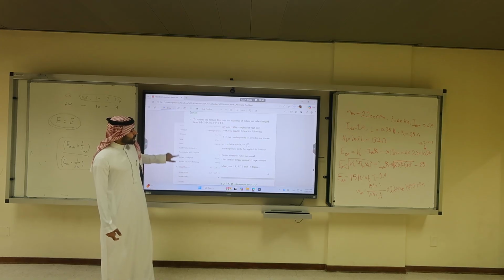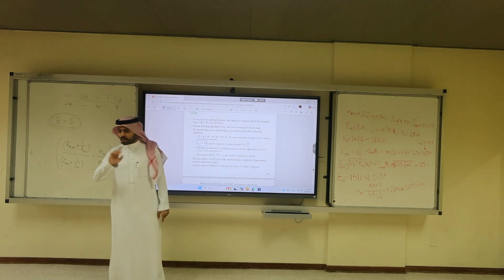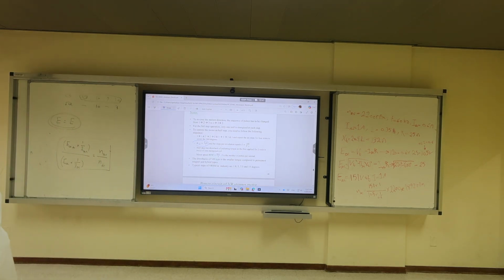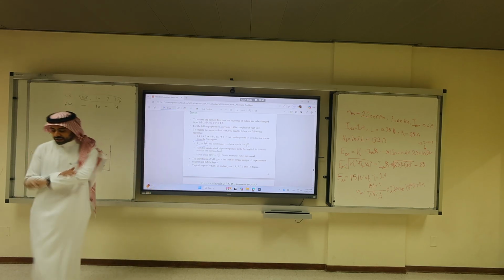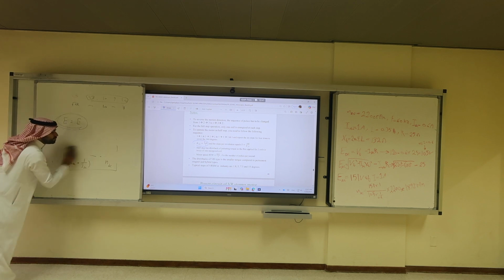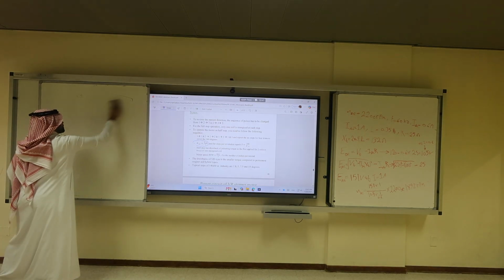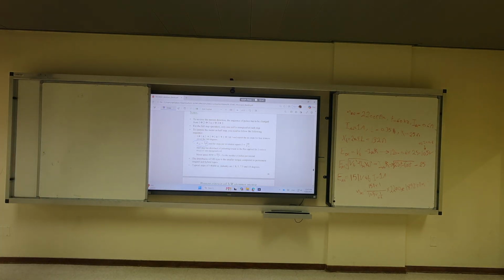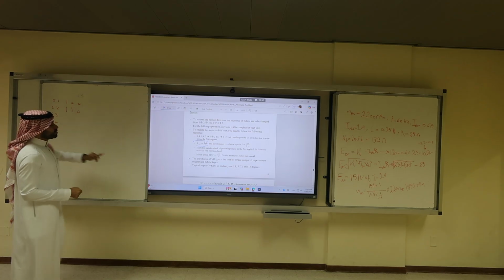Now half step has the drawback of pulsating torque. This is the only downside, and it is very important. Why does it have a drawback? Let me explain it. The problem is if you have steps 1, 2, 3, 4, how much was it here? 1, 0, 0, then 1, 1, 0. The half step.